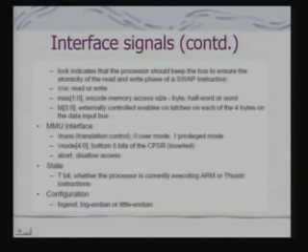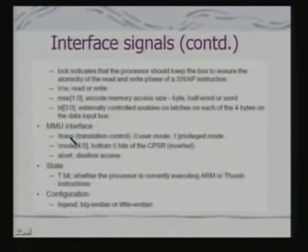So memory partitions, virtual memory, all these things are managed by the MMU, and these are the interface signals, because the MMU needs to know whether it is a privileged or non-privileged mode. It also needs to know how to do the address translation, because if it is virtual memory, appropriate address translation has to be done. Also it has to indicate the abort signal, that is, whether this location is disallowed access or not.